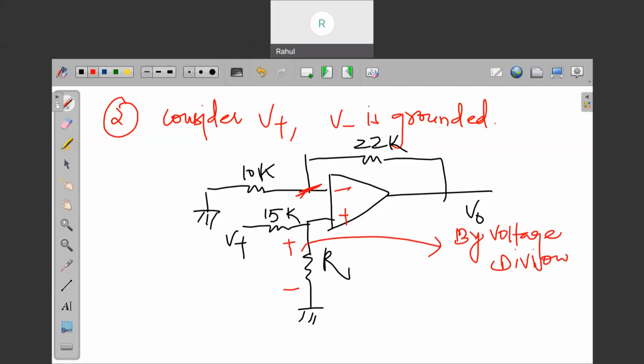Why are we applying voltage division over there? Because the op-amp does not take any current, right? The op-amp will not take any current, so these two resistors will be in series. So at this point, what shall be the voltage? The voltage will be V plus times R upon 50 plus R, right? 50 plus R. So what you can do now...